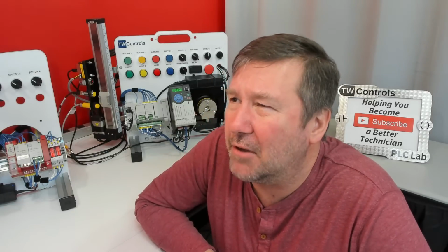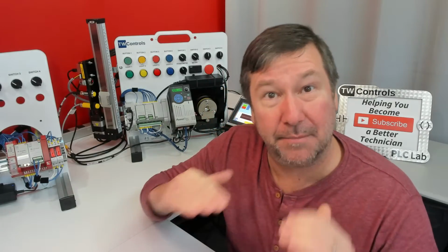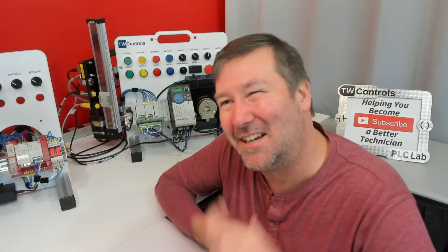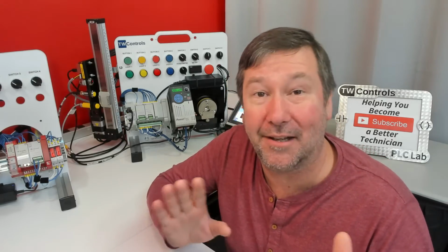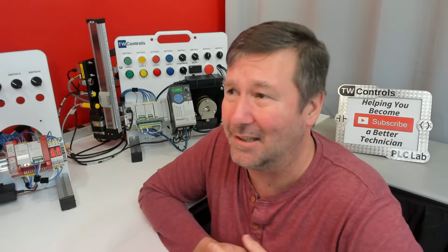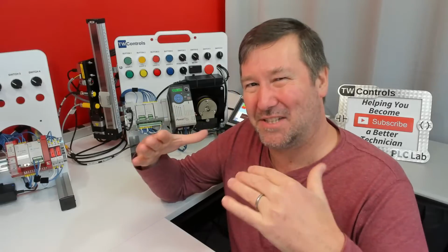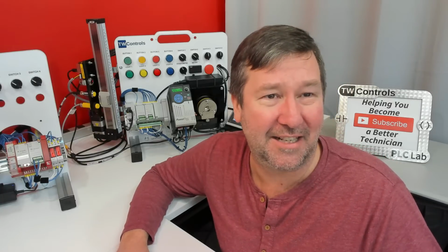But probably what I see new programmers do, mainly because they glaze over my PLC scan video, and that's 100% of why, is they don't fully understand how the PLC scans. And so they're over-relied on latches and unlatches. Nothing wrong with latches and unlatches. I know a lot of you out there are like, no, we don't allow them in our plant. I'm like, okay, are there any other instructions you don't allow in your plant? I mean, we need to understand them. But since we don't understand how the program really scans, we don't know how to sequence machine logic, then we're over reliant on latches and unlatches. That's a really good one.